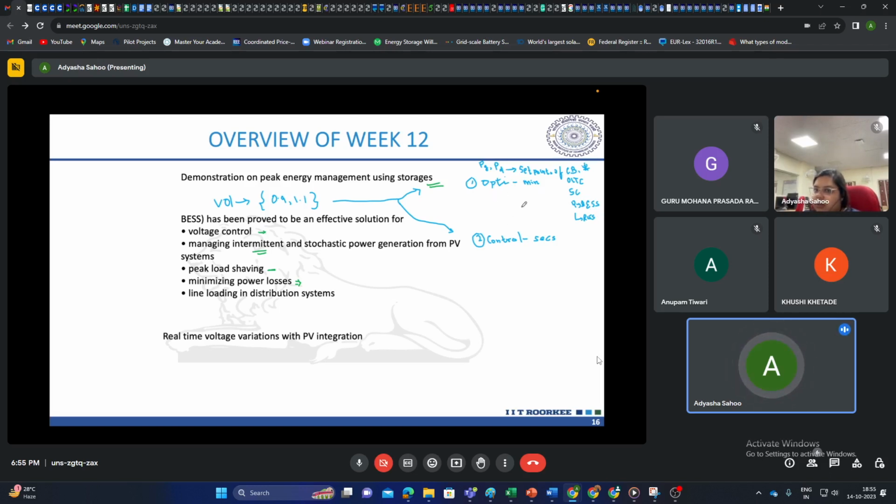After that, what may happen is, let's say when you come to the real or actual stage, right? So this was, let's say, t equal to minus 5, t equal to 0. So at t equal to minus 5, you had some information about generation and demand, considering which you run the optimization model and you get the set point for t equal to 0.